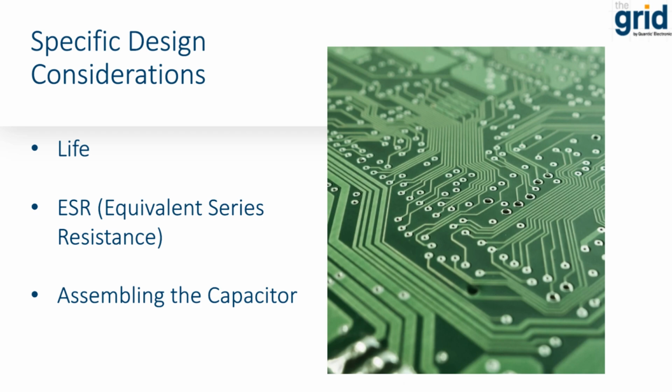The equivalent series resistance, or ESR, of a capacitor is a major factor determining its suitability for use within a directed energy system. ESR is the internal resistance that appears in series with the capacitance of the device. ESR values range from a few milliohms to several ohms, resulting in power losses, reduced efficiency, and instability of power supplies and regulator circuits.